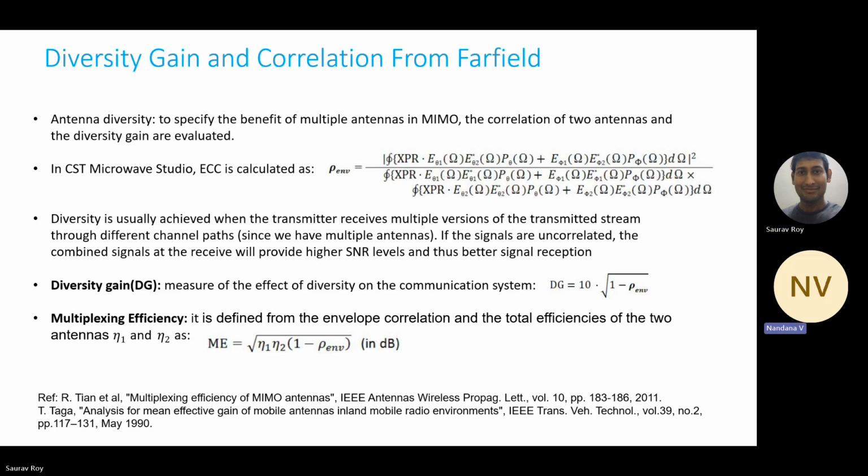So in wireless communication, we are mostly considering the SINR, no? Why is it so? Here we are considering only signal to noise ratio, right? So where does this noise come from? This noise comes from the receiver itself. In the receiver chain you have the antenna, then the down converter, the amplifier, all this, right? So all of this will add some noise.